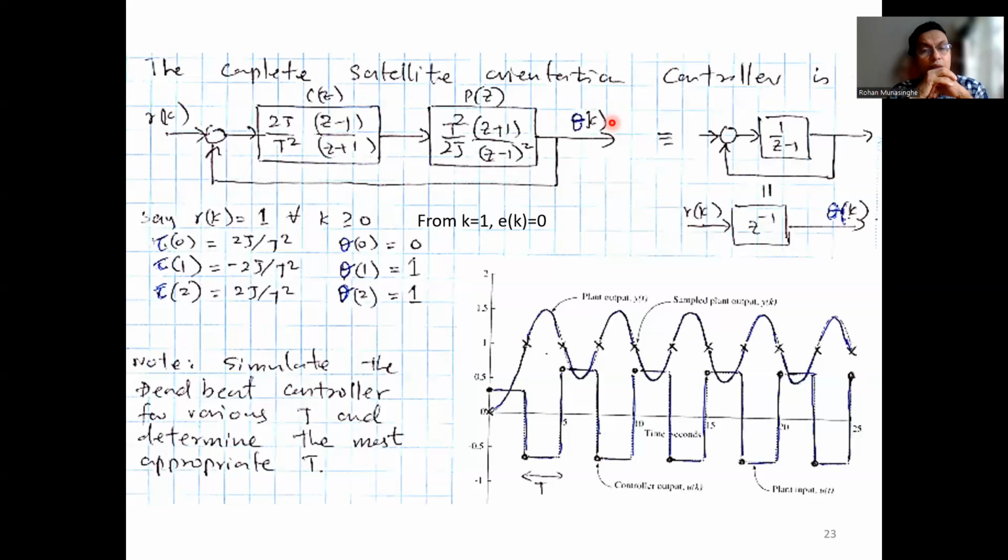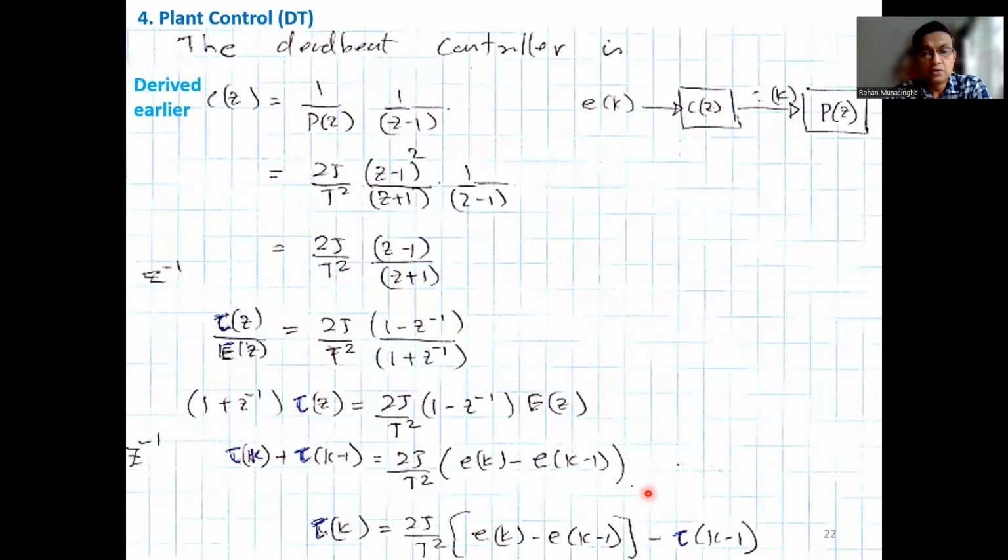So now if we get going with this one, Rk equals 1, and put it into the torque equation. I think it's over here. Yeah. So put Rk, Ek, that is error, initially is 1, and all these things are 0. Torque k minus 1 times 0, right? At time 0, the previous torque is 0. We don't know anything about it. Error, previous error, we don't know anything about it. It's also 0. Anything we don't know, we set it to 0, right?